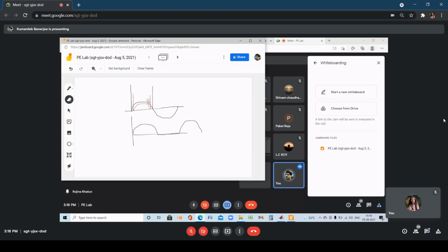So we can always find the time from the oscilloscope plot, but how do we find the angle? It's a simple unitary method conversion. So you write that 10 milliseconds is equal to 180 degrees. So 1 millisecond is equal to 18 degrees. So 10 minus 2 Tg is equal to how much? So first you find out Tg, you find out what is 10 minus 2 Tg, and then you write down what is the conduction angle for this value of Tg. Clear?